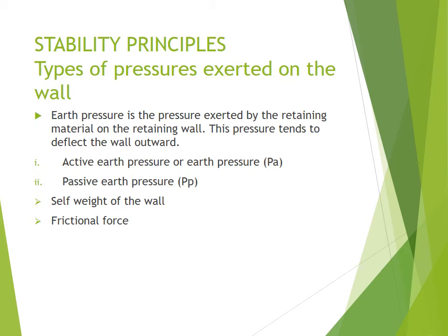It is the force acting against the base of the wall by the lower level ground and is created by the tendency of the wall to slide. And when the wall slides, it is due to the passive earth pressure that acts beneath the retaining wall and the active pressure that is acting above the wall due to some retained materials.